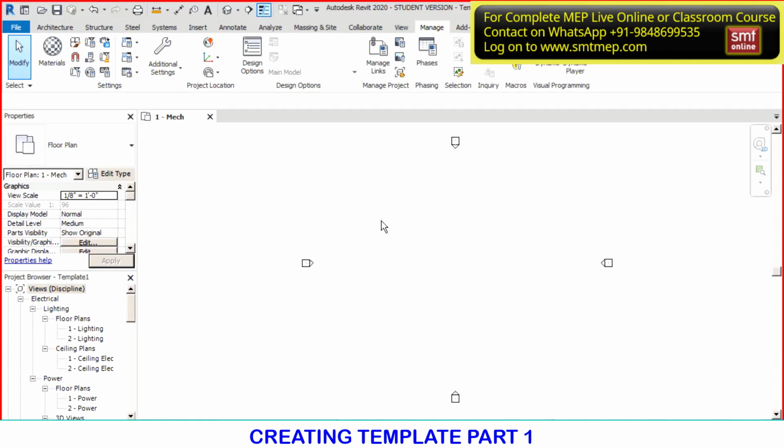The parameter you can find here. When you click on the screen, you see on the left side the properties. When you select any component, you'll find the properties on the left side in the Properties window. At present I click on the screen, this 3D model view, and the left side shows the model view properties. When you scroll down, you can find Subdiscipline, which, as I said, means services. When you click this drop-down, you see HVAC, lighting, plumbing, power, etc. Under the main discipline Mechanical, you can go for subdiscipline HVAC, plumbing, etc. Electrical means you can go for lighting, etc.